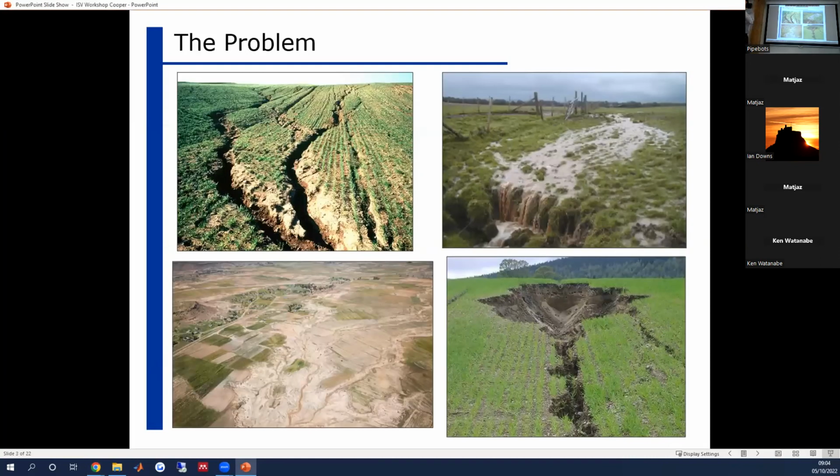The issue is these flows are very shallow. We're talking about a few millimeters up to a few centimeters. In terms of relative submergence, which I define as the depth of the flow divided by the roughness height, the flows are predominantly at a submergence of less than 1, all the way up to around 5. So quite different from what you would see in an open channel flow or a river flow.